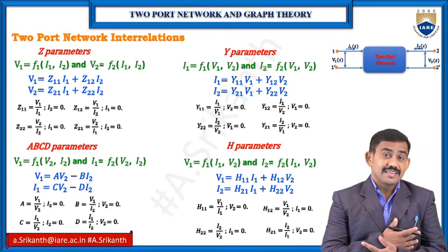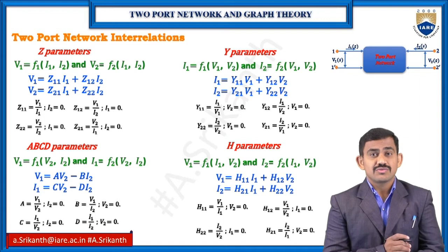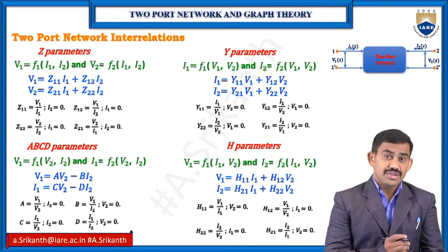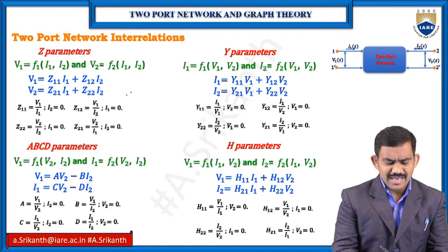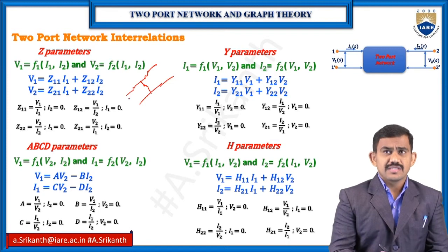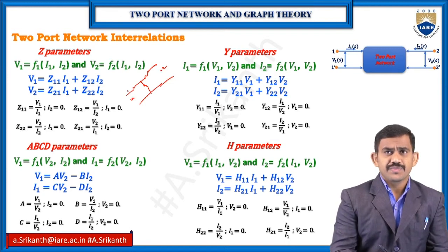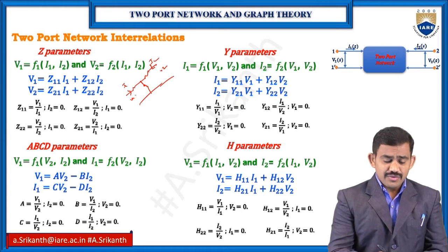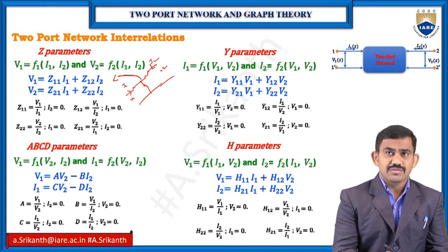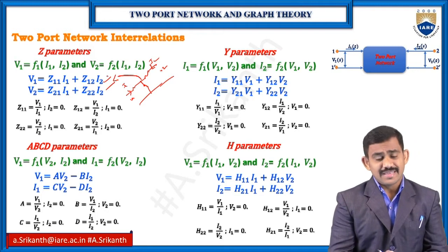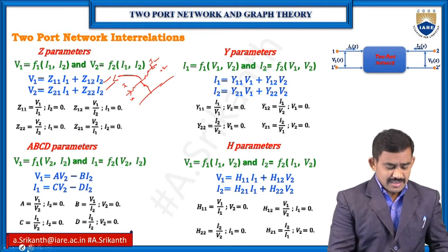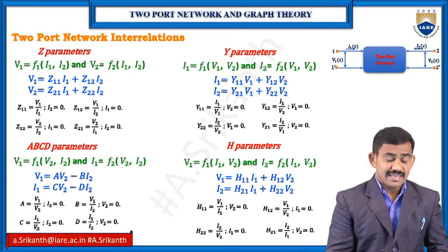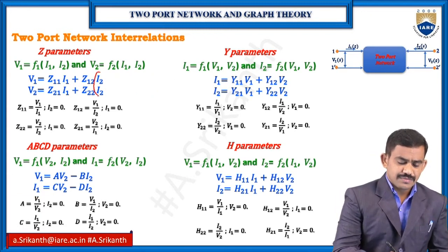I want to find out the impedance values like Z11, Z12, Z21, Z22. For this, you can use any circuit. Suppose here I have this circuit, with V1, V2, I1, I2 values. Now to find out the impedance values Z11, Z22, from this circuit you can write the two equations, then compare those equations and get the answers. Otherwise, if you know the conditions, suppose here I2 value is 0.